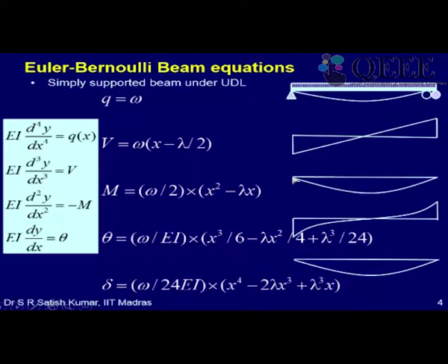So the bending moment diagram has to slope very steeply down, and then as it continues, the shear force becomes smaller and smaller, so the steepness will reduce until at this point the bending moment becomes maximum. Where the bending moment is maximum, the shear force is 0.